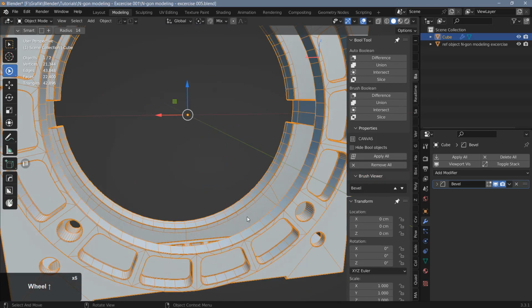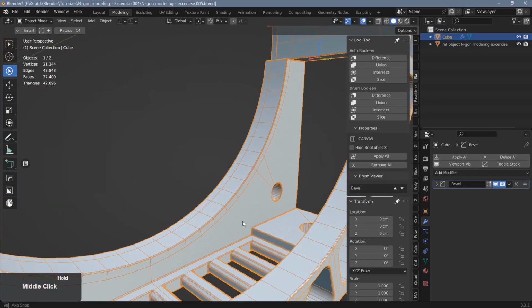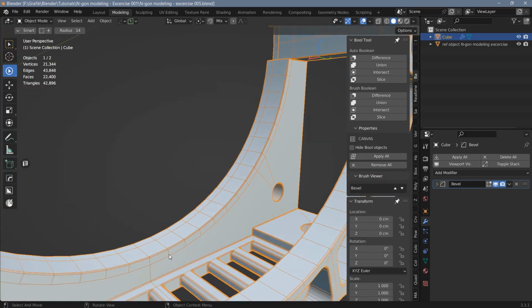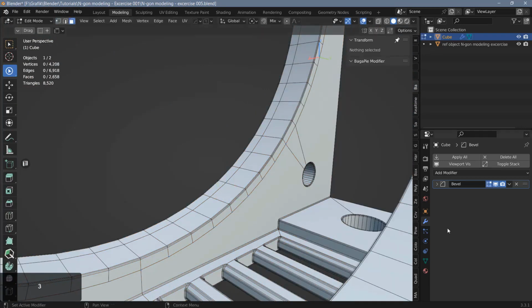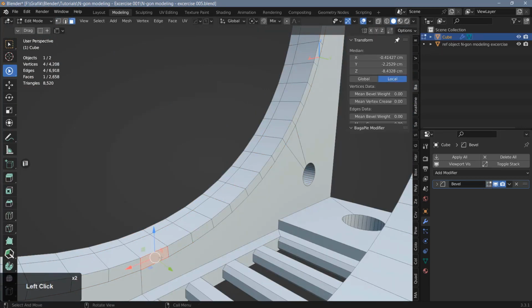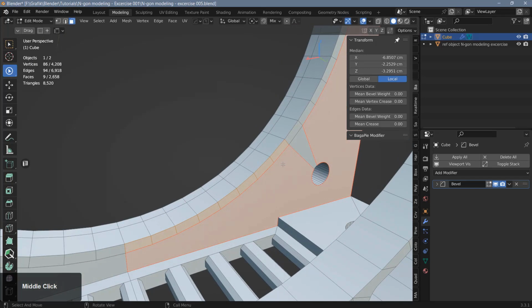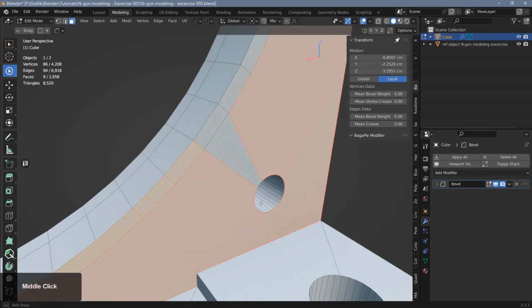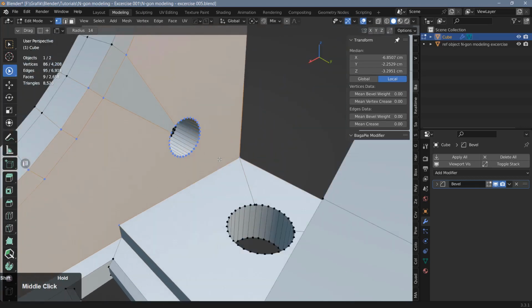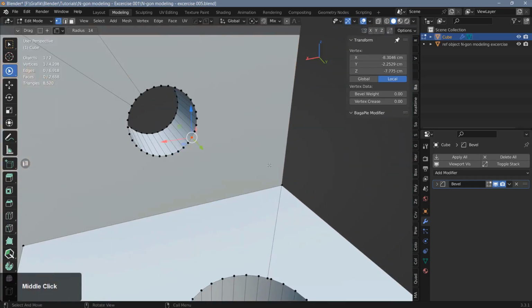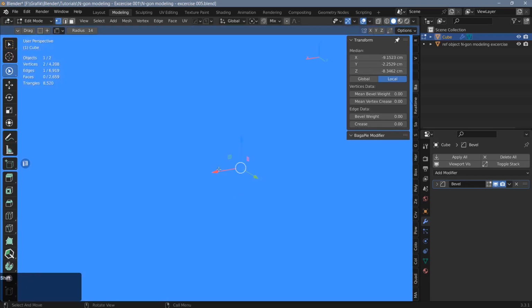There's one more thing we could do in order to wrap this up. Here at the back of the front wall, we don't need all of these faces here, so what we could do is select these ones and this one, and we do need two connections here. Actually, I think I'm going to change the connection here as well and create basically one in the corner here by joining these two vertices.